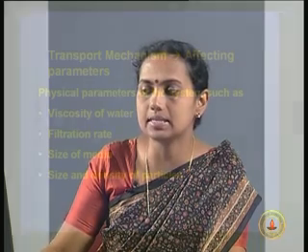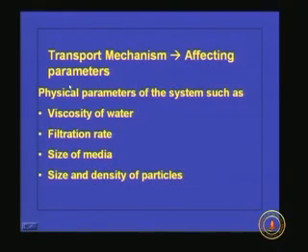And in the attachment step, once the particle comes in the vicinity of the filter media, it gets attached to the filter media and is removed. That is known as the attachment step. So, we will see what are the physical parameters that affect the transport mechanism. Those are the viscosity of water, filtration rate, size of the media, size and density of the particle.